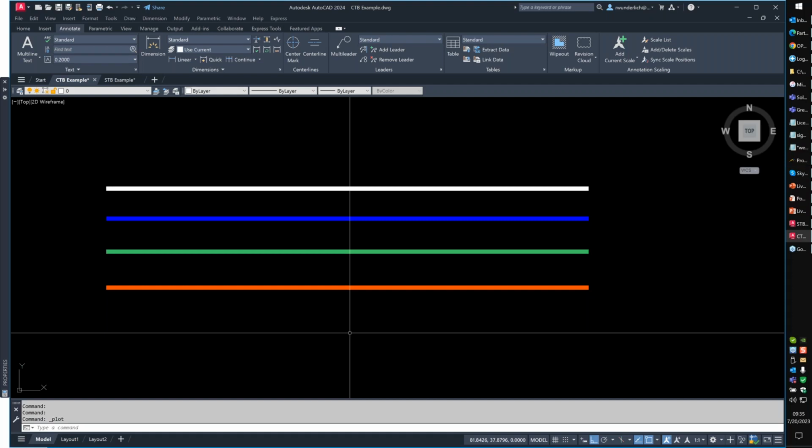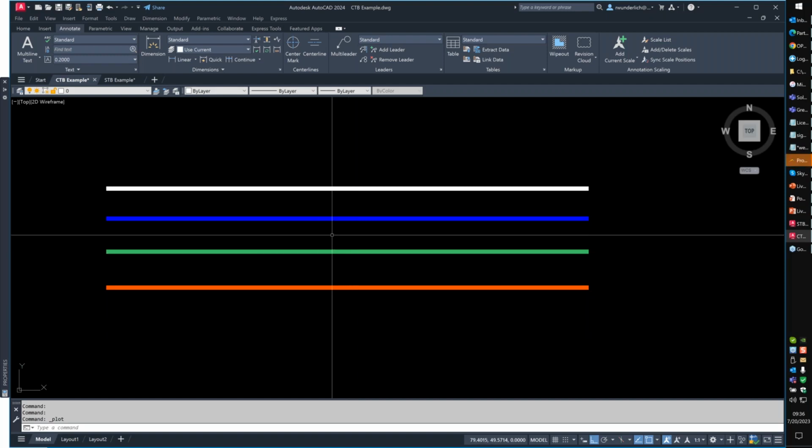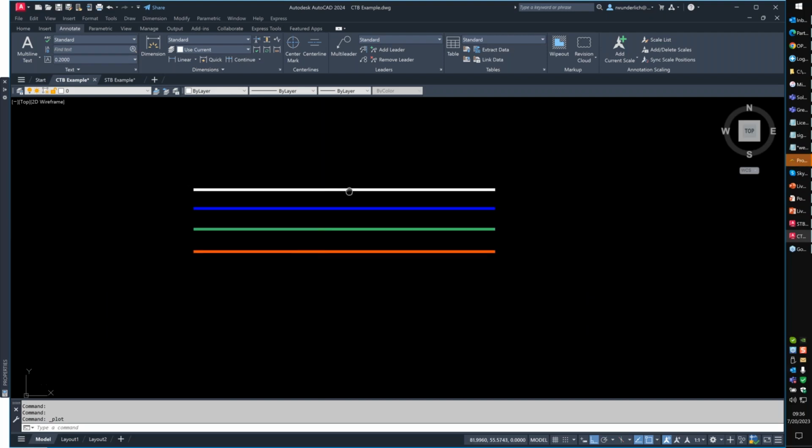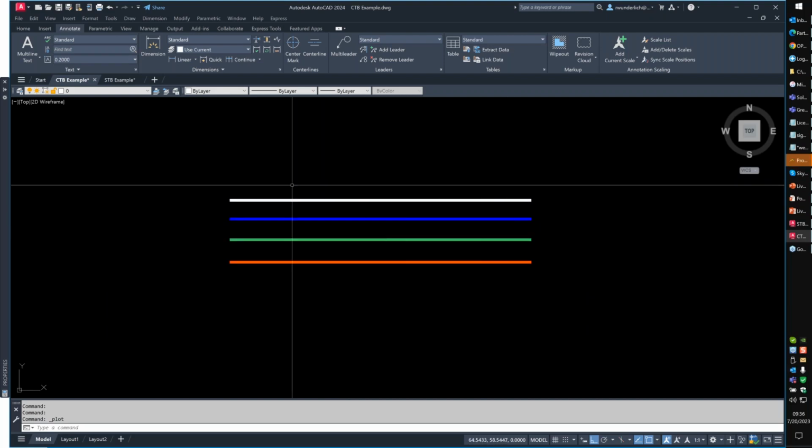Is there a way to plot a dumb PDF? Topo drawings are a beast. That's a good question, Sharon. I'll be honest with you, the best way to plot a dumb PDF is probably not to use the out of the box and use something else like Acroplot, Bluebeam, Cute PDF come to mind, something that strips all the vector geometry out and turns it into just a dumb raster-based PDF. So that's CTB and STB and the differences and how to go from one to the other.